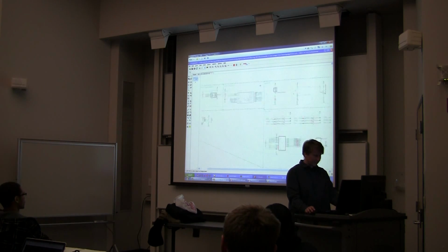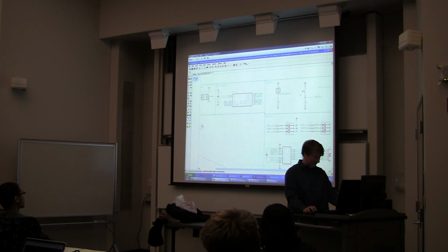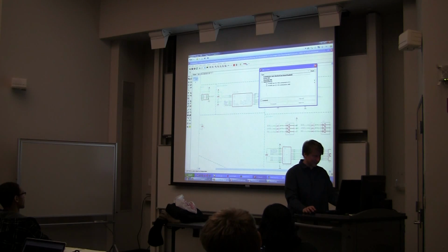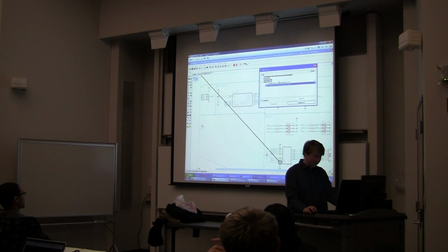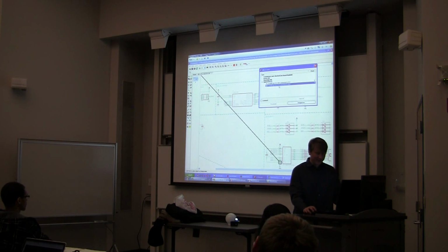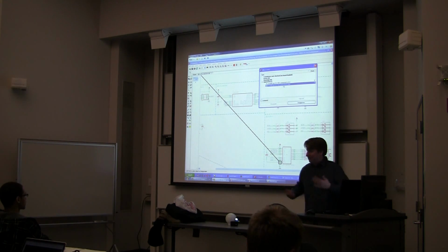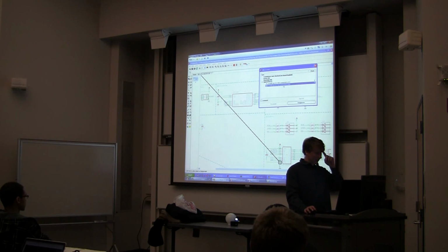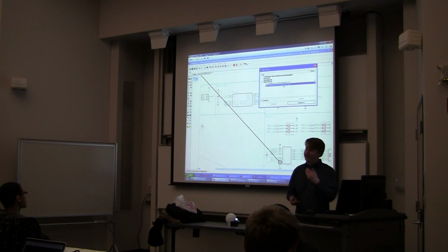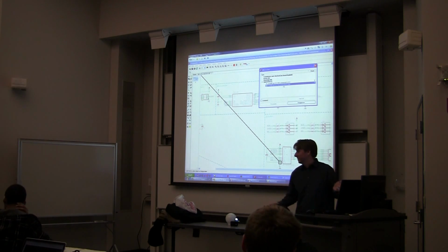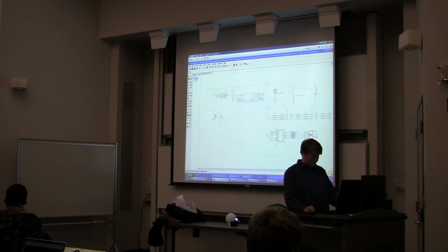Okay. Now let's see what we get. Errors, no errors, that's great. Now the two weird issues about VDD being VCC and VSS being ground are just two conventions that we're mixing. If I had made my entire board using VDD and VSS, that error would not have shown up. Okay.